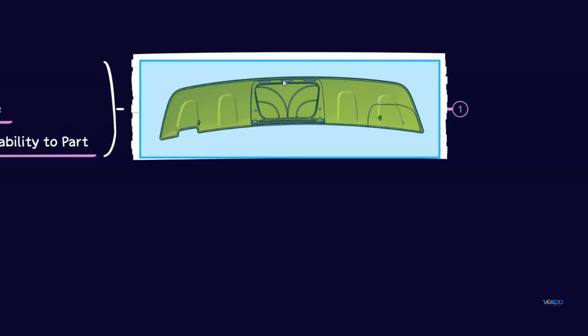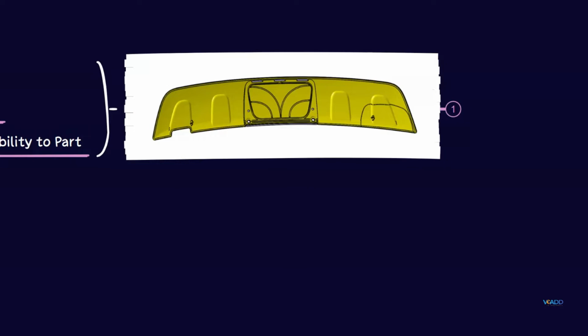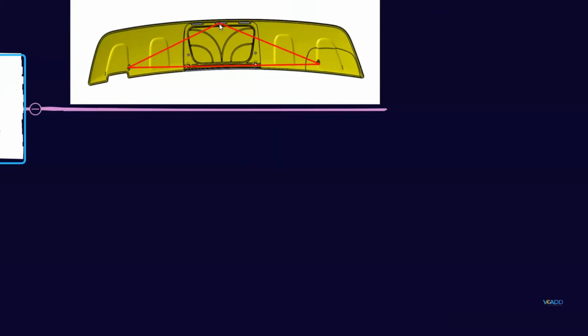So the general concept of creating the attachment is it should create a triangle, right? If your part is bigger, I'll just show it in this next image. You can see this. Here there must be an attachment, here there must be an attachment, here there must be an attachment. So these three attachments are a must, and according to the requirement you can create extra attachments in between. That means your part is locked here, here, and here. So you have decided the position of your attachment.